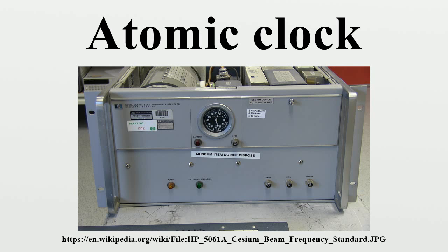Hydrogen masers have superior short-term stability compared to other standards, but lower long-term accuracy. Often, one standard is used to fix another. For example, some commercial applications use a rubidium standard periodically corrected by a global positioning system receiver. This achieves excellent short-term accuracy, with long-term accuracy equal to the U.S. national time standards. The lifetime of a standard is an important practical issue.